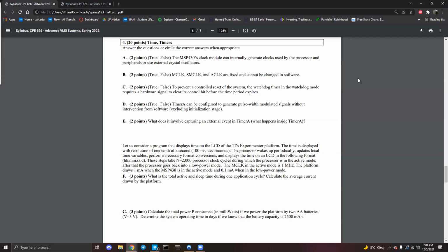It's asking, basically, can you use hardware as well to achieve this? We know we can do software, but you can use hardware as well, as Sydney said, with external capture and control stuff, hardware blocks, where you can give it a reference or information on some pin. I think we did that in the lab with the buzzer, because we had the buzzer directly driven by the timer pin. I think there's also the fact that you can set the multiplexed register pins as output or input, right?